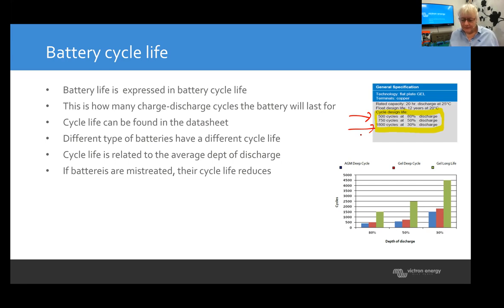And that's also again the case for lithium. Lithium has got much higher life cycles. So if you have a system that needs to be cycled every single day, like an off-grid system, like an ESS system, like I have, maybe in a commercial vehicle that's being used every single day, like a coffee vehicle, ambulance, all those sort of things, the batteries are consumable.